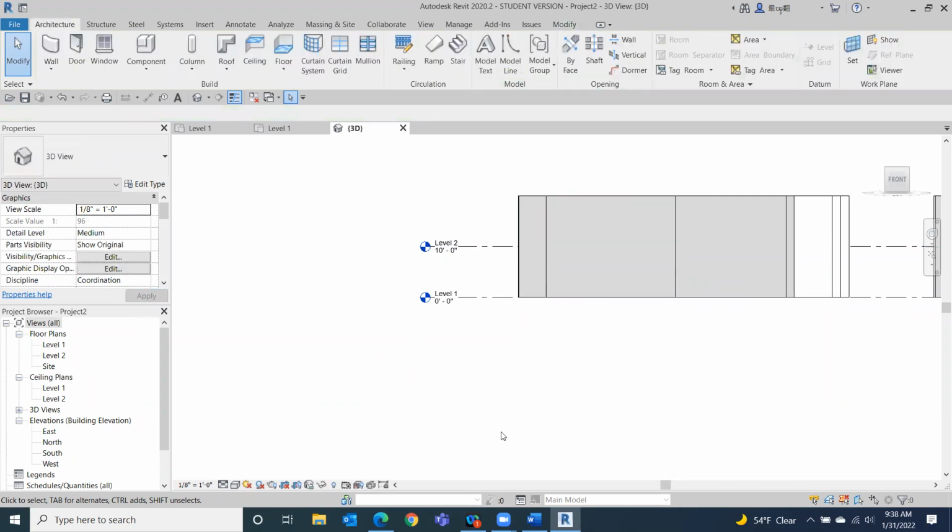When you're doing your walls initially, and they come out to 20 feet when you create them, leave them at 20 feet. Don't change them to 10 feet or anything like that. Leave them at 20 feet because it's part of the process. I kind of show you how to work things, so you don't have to change your walls when you're creating them. We'll come back and add the roof to our 20-foot wall, and then we can show you a different way to connect the walls to the roof. So you do not have to change the height of the walls as you're drawing your initial walls.